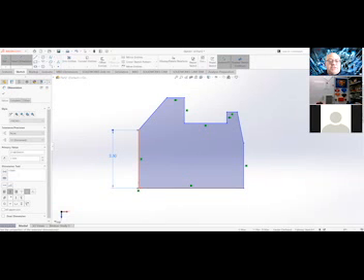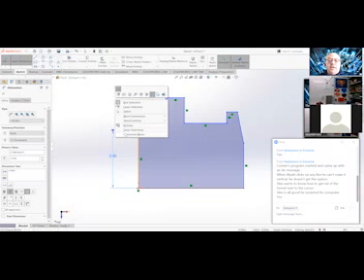So here's your dimension settings on the side. We'll get into those much later. But I just want that 2.5 there. That's the only one I need. Then right click and I make sure everything's there. This is where you'll probably find your filters if you get into those. All these sketch entities are here, so if you get into this area, you could easily filter. The escape key is how you get out of it.